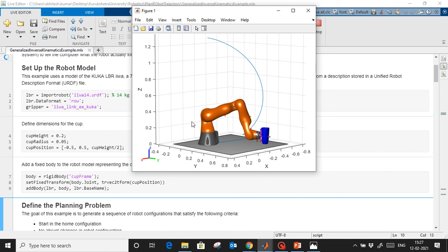So once I am happy with that, if my verifications are done, testings are done, then we can go for the hardware part modeling, right? And the controller which is used, either here no controller is used, here it is an open loop. So that's why we use the solver to solve this. Instead of this, we can use some kind of PID controller. For that, we require this exact data, how this will be moved. We can give it as a reference, and at the output we can check whether it is following the same path or not. That's the easiest way to do that. So here it is animated, showing it moved like this, then here, from here to here, right?